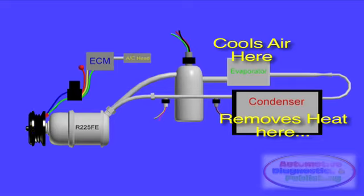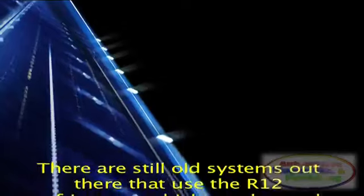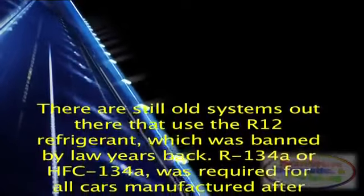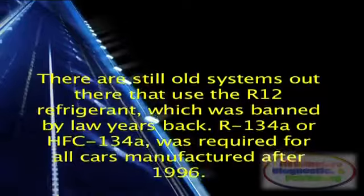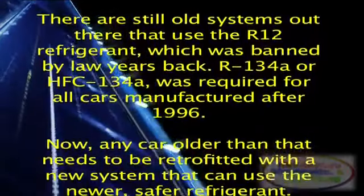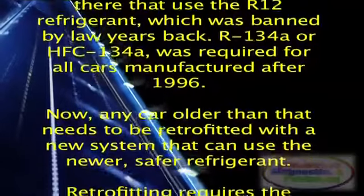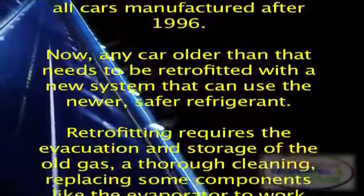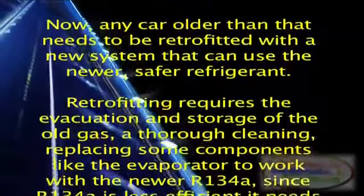Different refrigerants are also in use today. There are still old systems out there that use the R12 refrigerant, which was banned by law years back. R134A, or HFC 134A, was required for all cars manufactured after 1996. Now, any car older than that needs to be retrofitted with a new system that can use the newer, safer refrigerant.